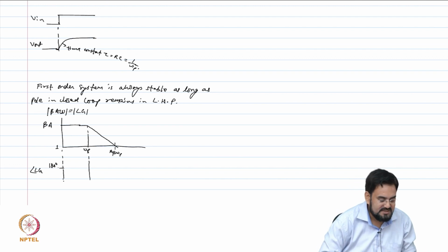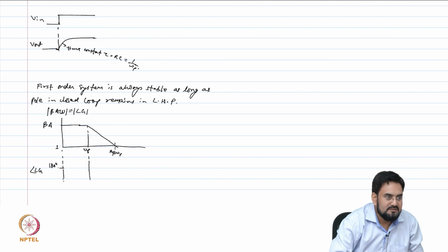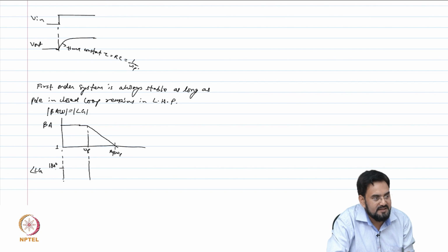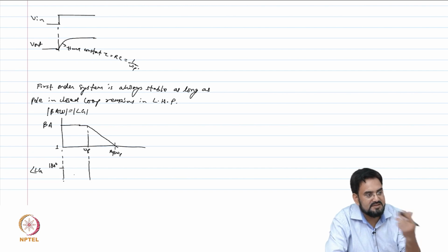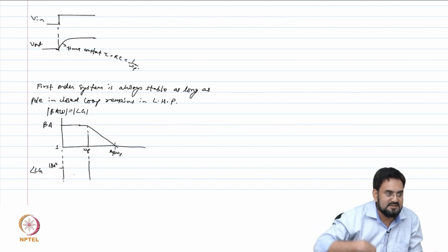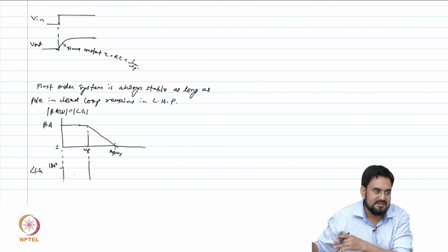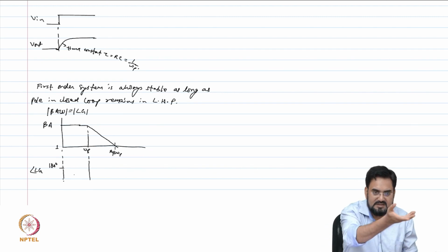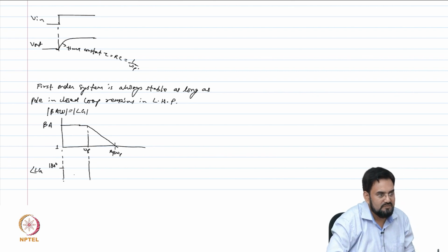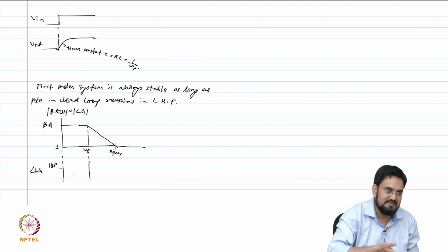In some cases, some people start with minus 180 in order to show, because a pole has a negative phase. Which means if you start from 180, you are going from 180 towards 0. If you start from minus 180, then you are going towards minus 360. Just show that your phase is moving in the same direction. Even in the simulator you might find it showing from minus 180 instead of 180, but it doesn't make any difference as such. Ultimately 360 is the same as 0 degree.